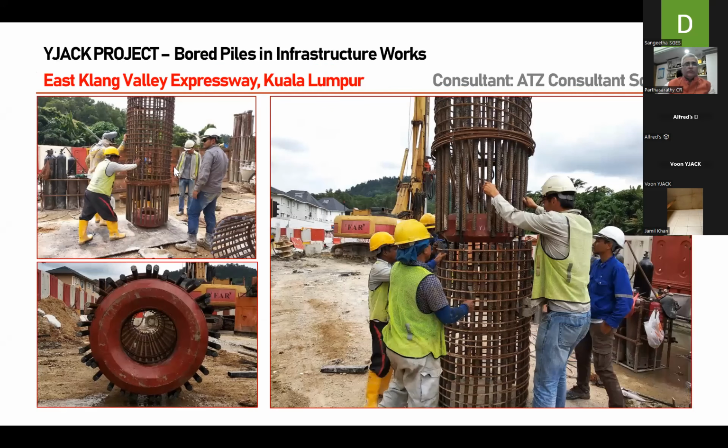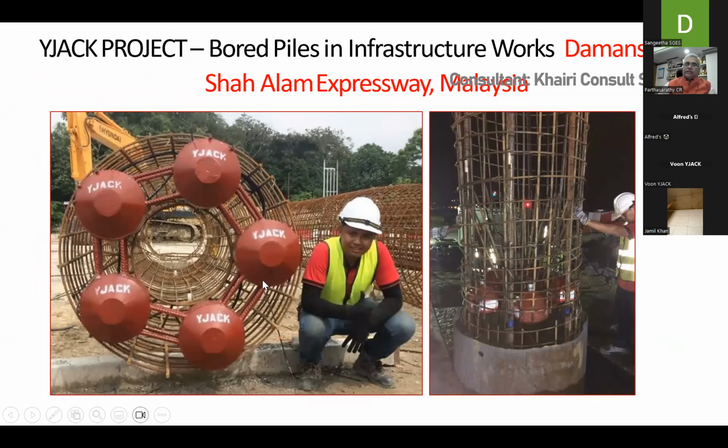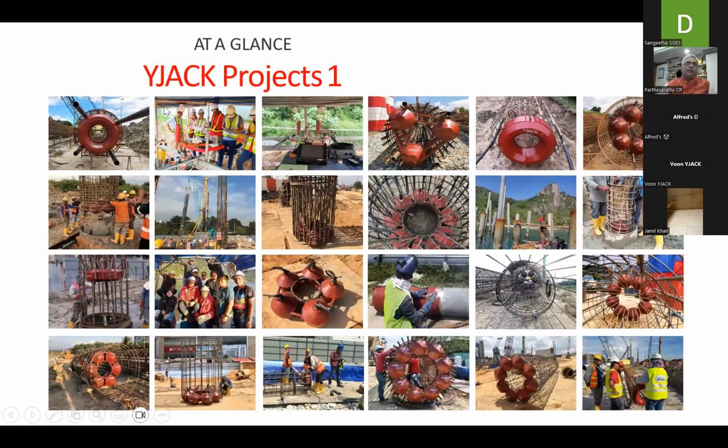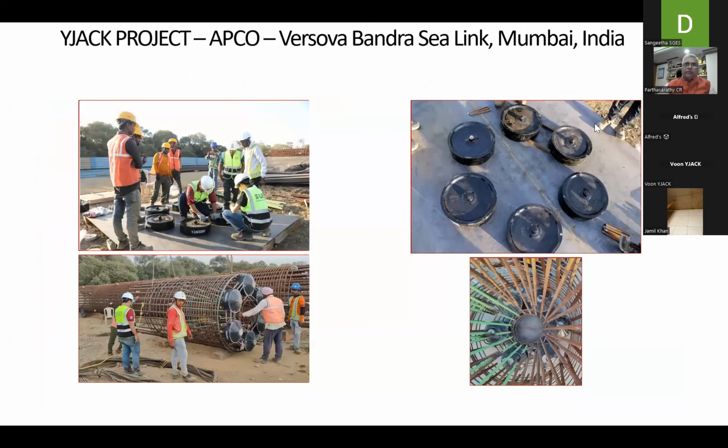Now you could embed this jack in the reinforcement. If you are splicing the reinforcement, you can do that and pour the concrete when it is ready, and then with the telltales you measure the displacement and apply the force. There are many projects YJack has performed in Southeast Asia, and we wanted to commission that in the Indian market as well. And recently we were successful in a couple of projects.